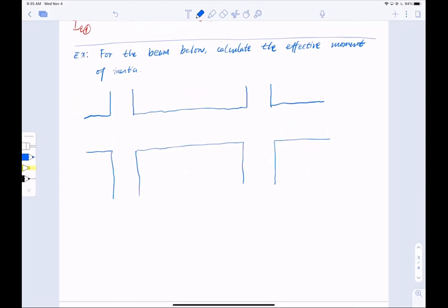This is a little bit tricky, but before I draw the reinforcement, I forgot, let me draw some dimensions. The clear span between the two columns is 25 feet. Now, from center to center, this is 26 feet. All right, so let's take a look at the reinforcement. Let me use black color to show the reinforcement.